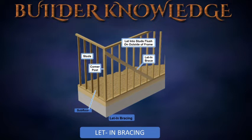Lead-in bracing. Lead-in bracing is usually made from 1 inch by 4 inch material, set diagonally from top plates to sole plates. For lead-in bracing, the studs are notched so that the brace will fit flat and flush with the surface of the studs. The studs are always cut to let in the braces; the braces are never cut.